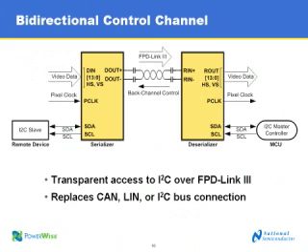So that might be, I guess, a camera, right? That's right. So in this case, the camera has some sort of ECU that's controlling it. It's acting as the I2C master. And oftentimes in older systems, without this technology, this would have to go to another automotive bus. They hardly ever run I2C raw over an automotive system. They'll take it to CAN or LIN. So there's additional components that are required.